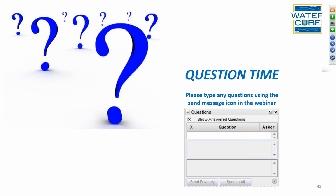Great. And there's actually a technical question, John, around the ADCPs that we've been looking into ourselves. In fact, for using ADCPs and the slant beams for bathymetry, do you worry about ray bending in stratified reservoirs affecting any of the accuracy of the depth? And so therefore, there's probably multiple instruments you can apply to something like this. But John, do you want to address that?